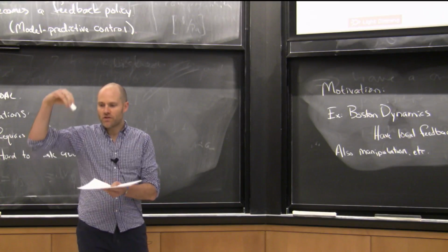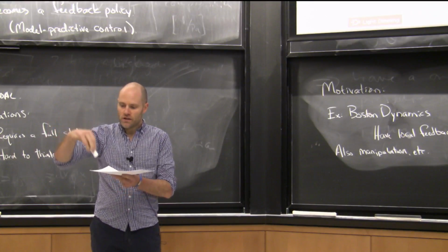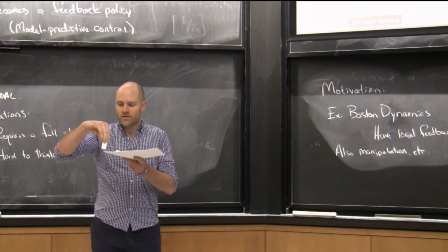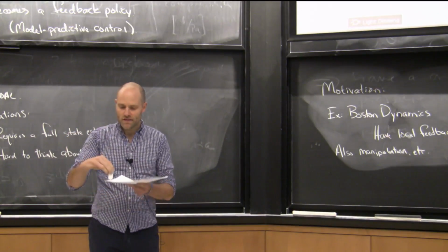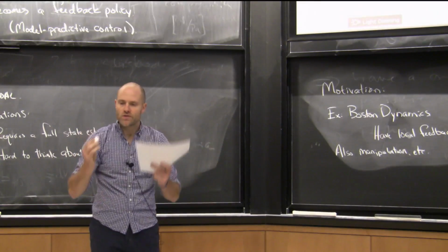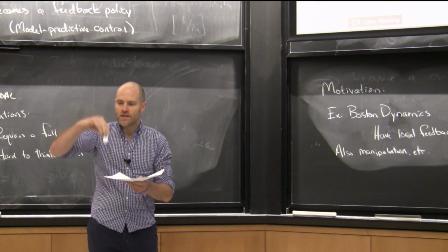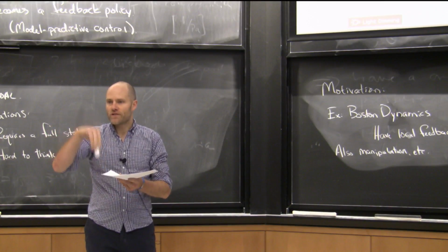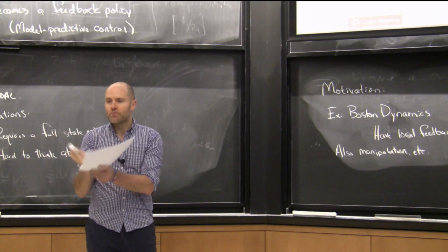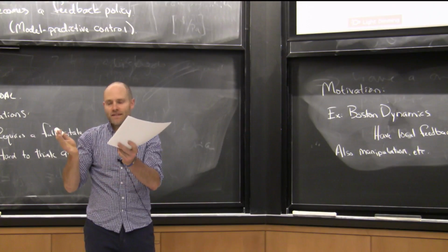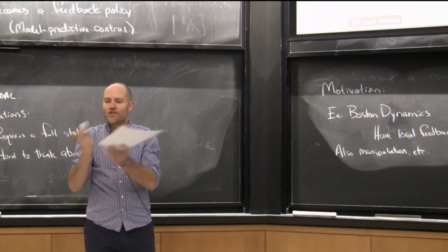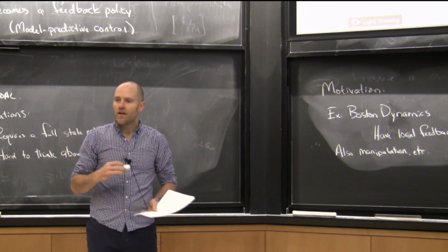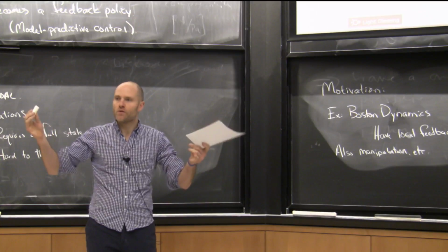And it talks about these guarded moves of how do you go down and touch the edge of the peg in order to insert robustly, and it introduced this idea that if I were to do this move, there's a set of initial conditions from which this move would actually accomplish some task. That's the pre-image of that move. And if I can back chain the pre-images of all of these potentially guarded moves, then I can somehow figure out what I should do from every initial condition.